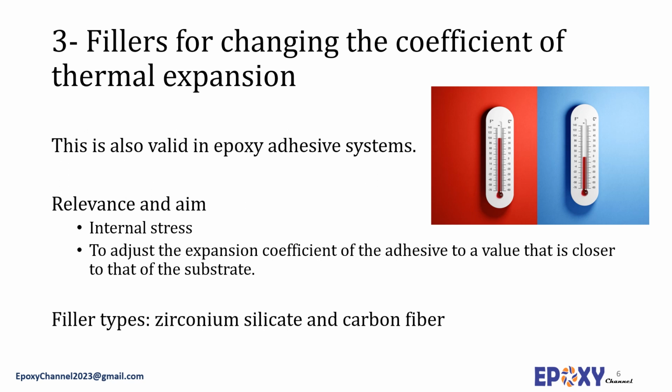It is usually not possible to employ a sufficiently large filler loading to adjust the thermal expansion coefficient required to match the substrate, as high loadings increase viscosity to the point where the adhesive cannot be applied or cannot wet the substrate anymore. For some applications and some fillers, loading volume up to 200 pph may be employed, but optimum cohesive strength values are usually obtained with lesser amounts.